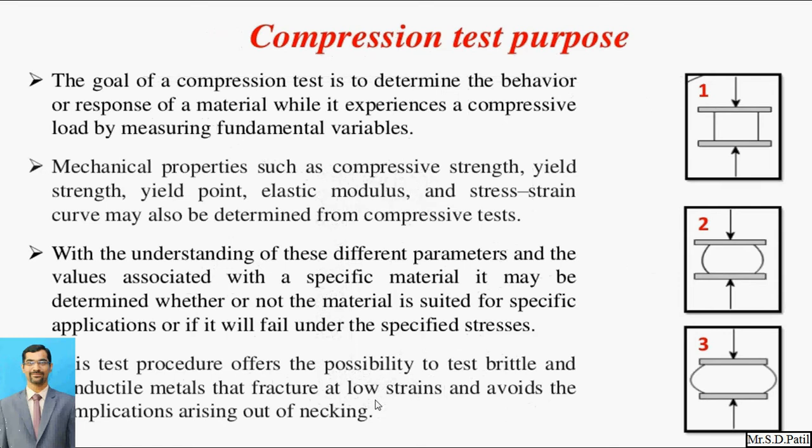Here we can see it is very interesting. Here I want to show you how exactly the compressive test is carried out, and what kind of failure pattern may be generated. So basically for the ductile material, this particular portion has been buckled over here. So here we can see this is the specimen. These are the two upper heads and this is the lower head.